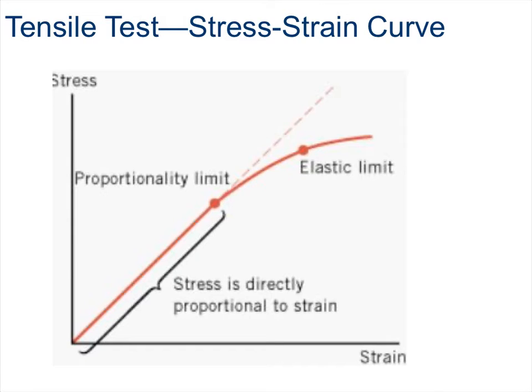This is because the elastic limit is the strain below which the material can regain its original shape if the forces are released. Therefore, it doesn't matter if the stress-strain relationship is linear or not. When a material is stressed beyond its yield stress point, it will experience permanent change in shape. As a result, the tensile test specimen is now longer than it was prior to loading or even after the removal of the load.